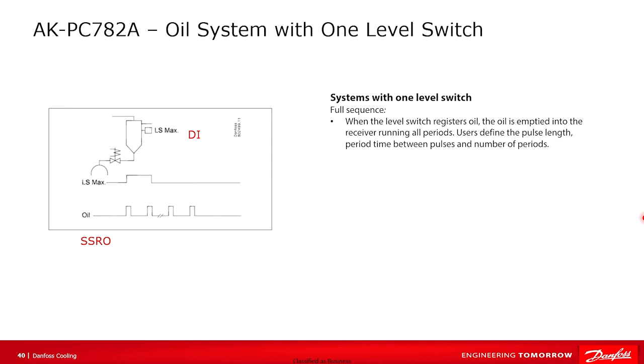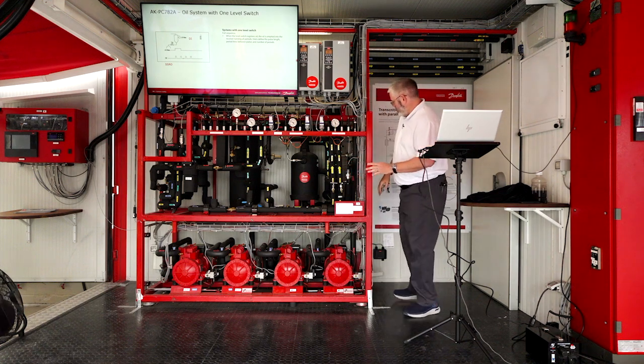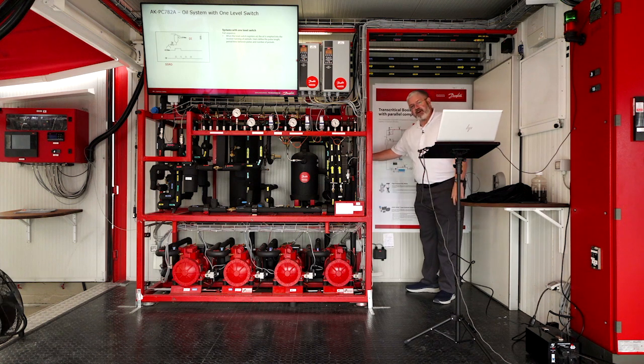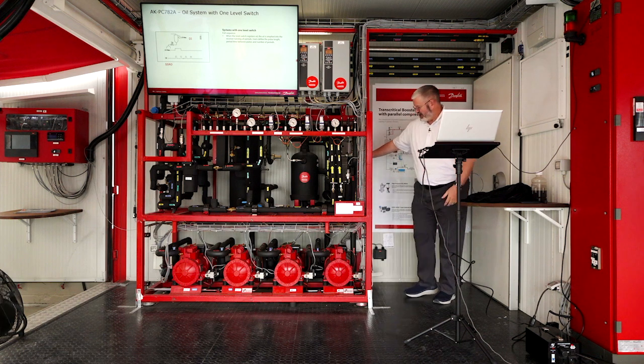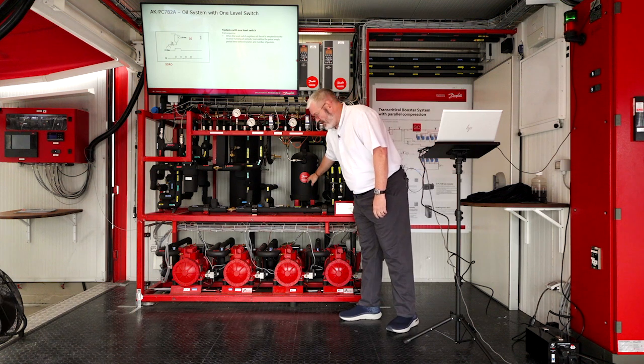So someone asked earlier about, is the oil system different? The first thing to note before we start going through slides, if we can get the unit view. So we have over here, and I don't think we need a close-up, Josh. We've got an oil separator over here, like a large Pringles can that we saw earlier. And then that dumps into this fairly large oil reservoir.